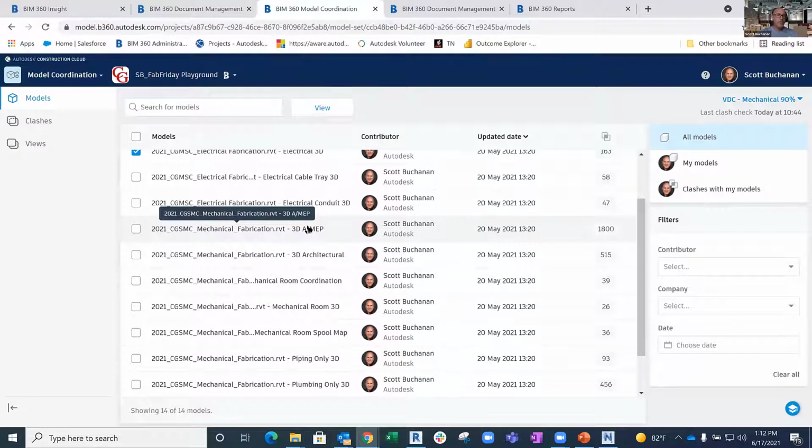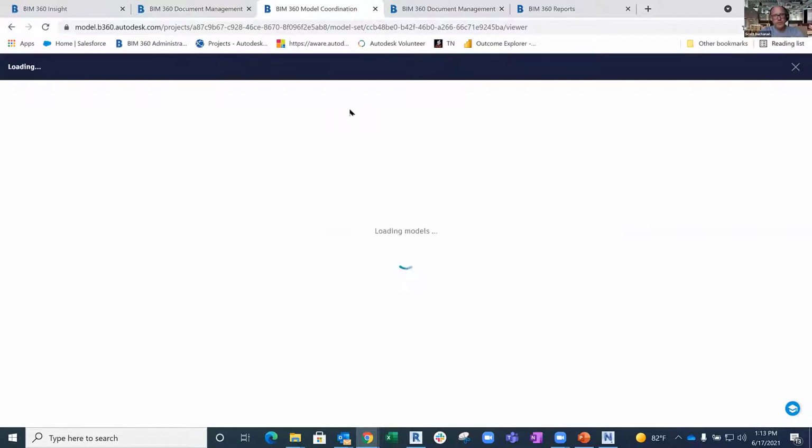For my Navisworks users, think about if you were in your Revit project and you had 3D views predefined in your template, called Navisworks exports, and you would export out an NWC for each of these different areas, whether it's discipline only or level only. I don't have these broken out by level. I should. I do in the live one, but not this one. So you'd be exporting out those individual NWCs and then aggregating them inside of Navisworks. Whereas inside of model coordination, it takes those 3D views from your publish and automatically extracts them, so I get to choose what views I want to pull, with that aggregate behavior.